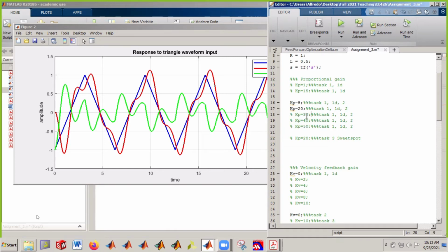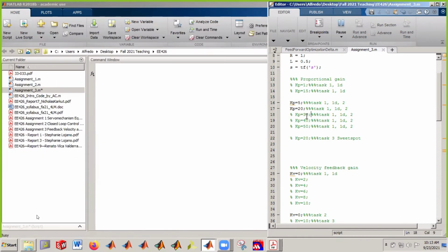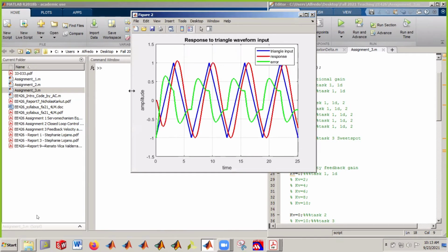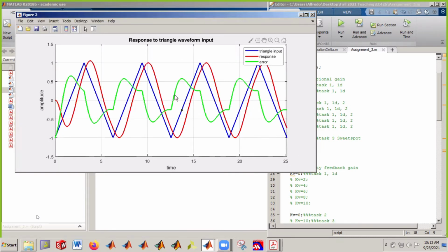Although there's something that you did not see when you were doing the square wave responses, right? And this is something you should pay attention to when you see this. We can say that this triangle waveform, if you look at this, it kind of has 2 phases, right? So it changes from a negative slope here to a positive slope here, the input, and you see this is how the system behaves here. But now, because the input is just steadily increasing without sudden changes, you can see that the red line, the motor, has enough time to come closer and closer to the desired position.